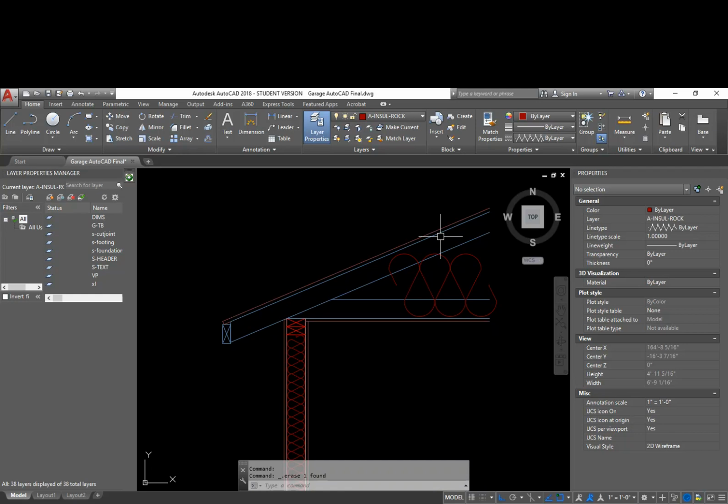not only to extend the life of the shingles, but to prevent ice dams. Basically what happens is, if there's heat in here, the heat rises, slowly makes it through the insulation, heats up any snow that's sitting on top of this roof, and then as it melts, it rolls down the roof, and once it gets to this part of the roof, the tail, has no heat under it, so it's very cold out here.